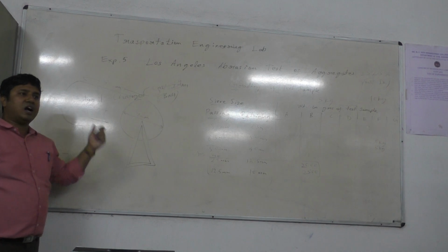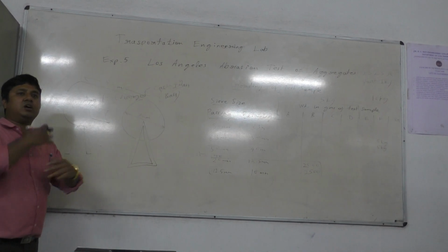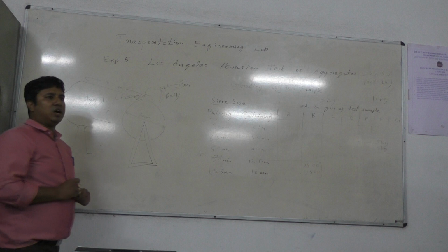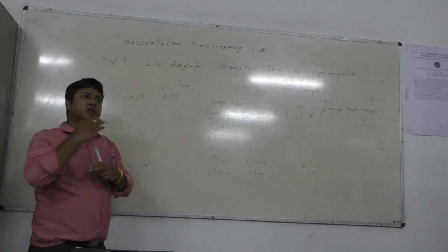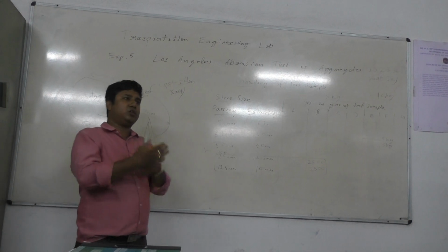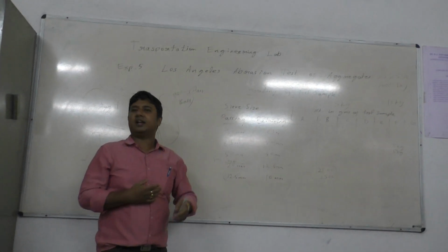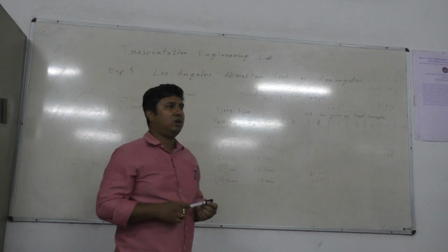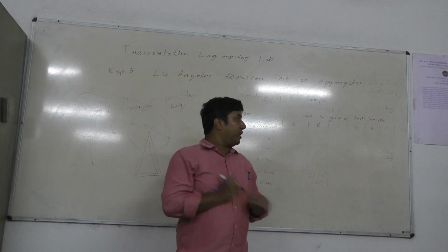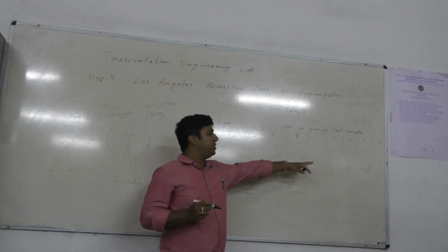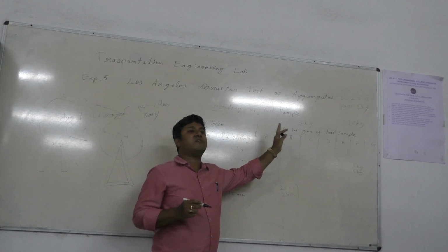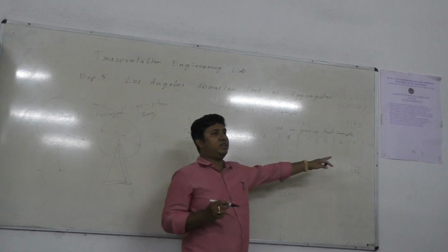Then we will start our motor, which will rotate the drum at a speed of 30 to 33 rpm, rotations per minute. The rotation should be uniform, there should not be jerking in a single direction. The number of rotations also depends on the grade we are using. For grades A, B, C, D the number of rotations is 500, and when it is more than this, it is 1000.